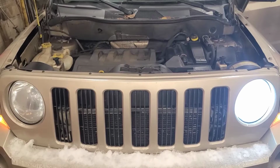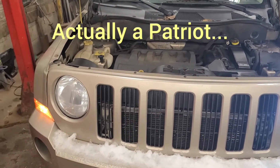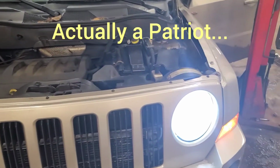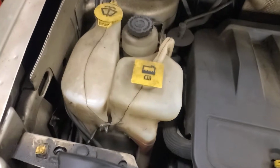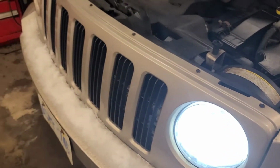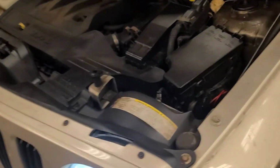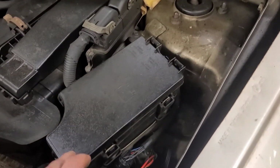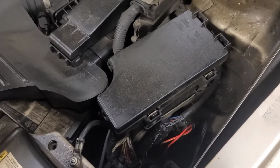Today we have a 2010 Jeep Compass, and as you can see, the right headlight doesn't work. The customer had this problem and then changed the headlights to LED with an LED kit, and it's supposed to be plug and play, and it still doesn't work. So he assumed that the bulb was bad, and these are controlled by the TIPM. So we're gonna scan it to see if there's any current codes for the headlight circuits.